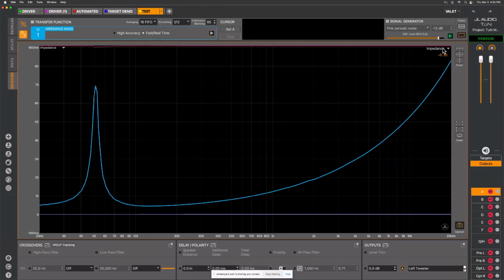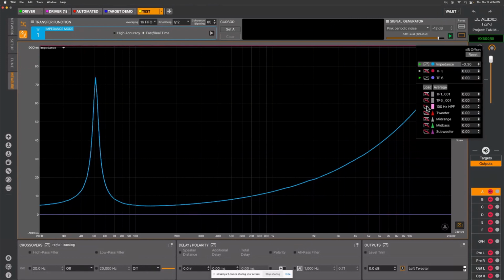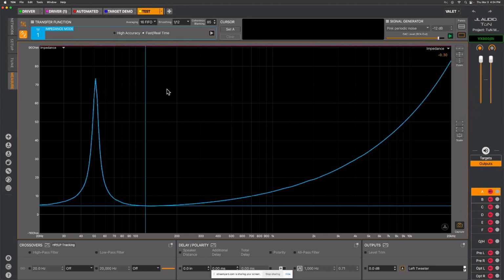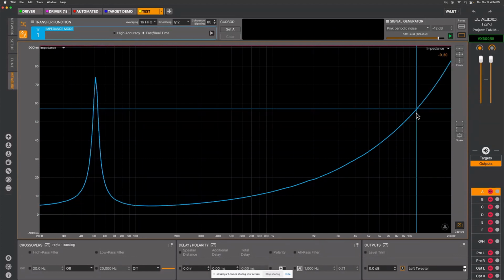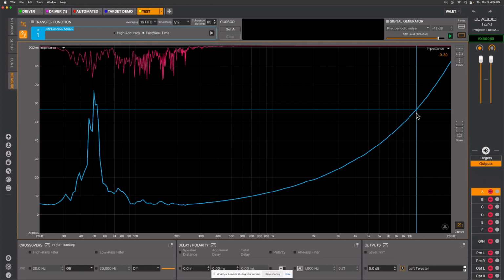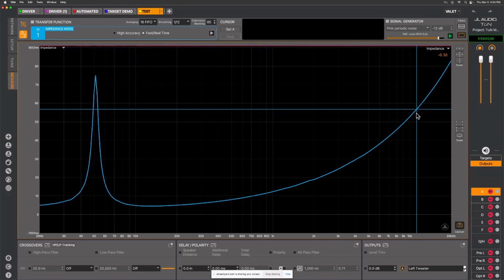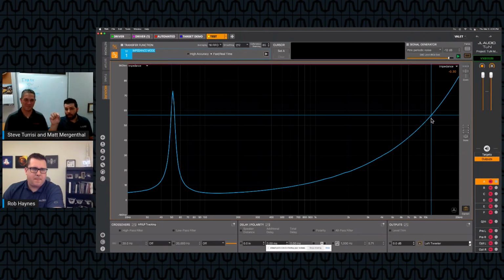Now, the hard part is that the speaker is sitting right in front of us. So as we talk, it may affect it a little bit because there'll be vibrations in the air that'll possibly affect it. So there's a couple things I want to do here. I want to capture this speaker and compare it to another speaker that we have next to it. See if they're the same. So this is a good way to test when you're working on speakers. If there's a defect with one of the speakers, you'll see it show up in the measurement. And we don't care necessarily exactly how it looks, just how it compares to the other speaker. Right.